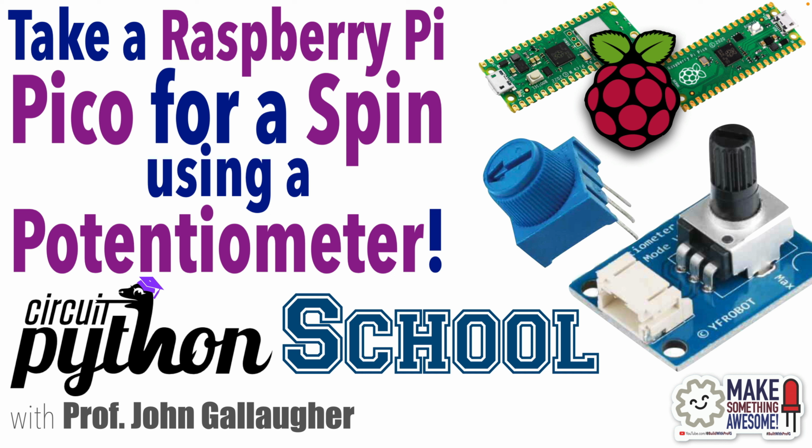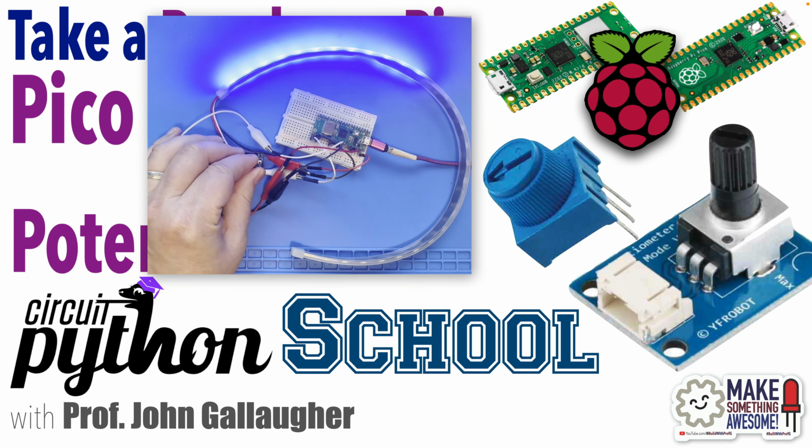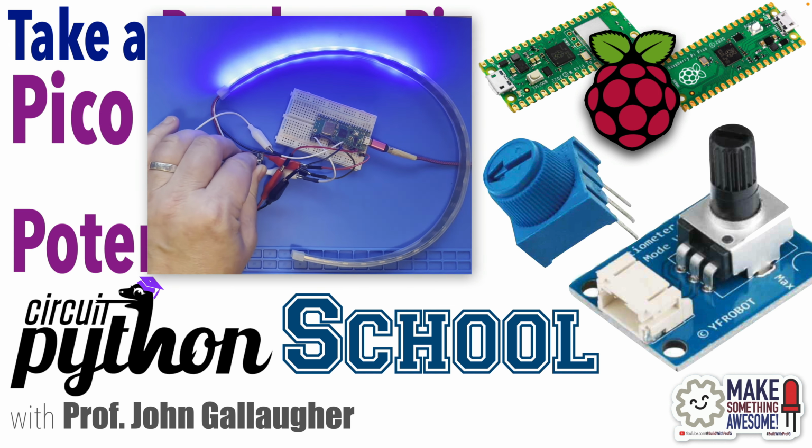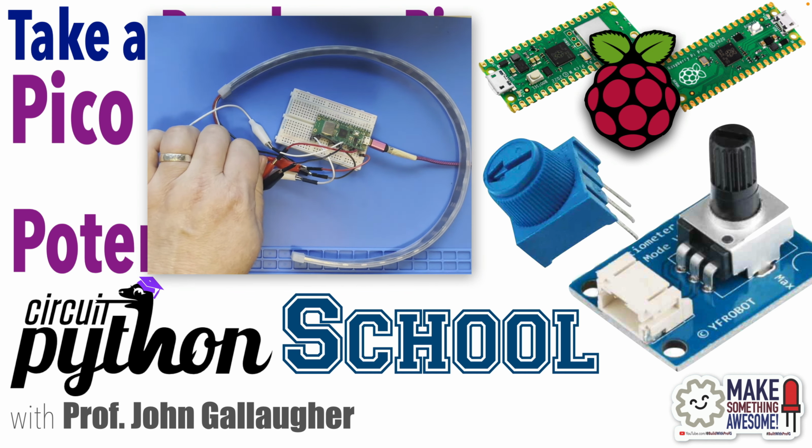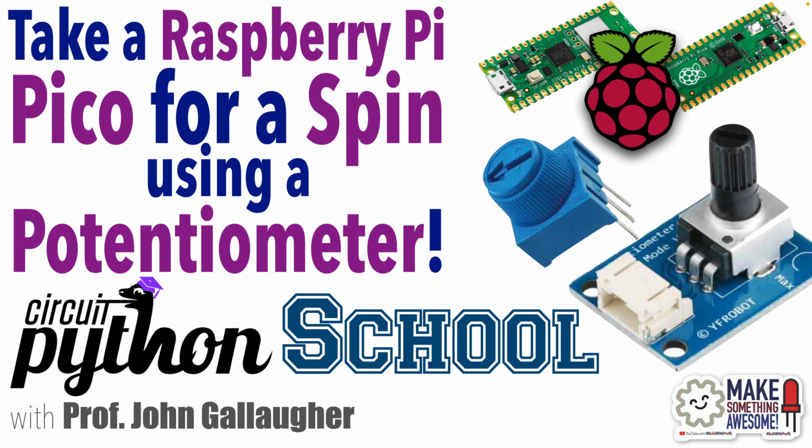Now we'll first show how to use CircuitPython to read values from the potentiometer, and then we'll have a challenge and show the solution to turn the individual LEDs in our light strip on or off based on readings from the potentiometer. And even if you complete the challenge, you should stick around and check out the solution I'll demonstrate, because I'll also show how you can use the Python concept of slices to quickly update LED lights on a strip without having to use any for loops at all. Let's spin up some big learning.